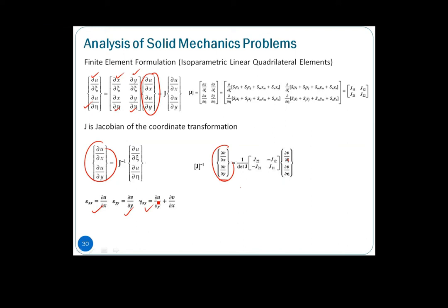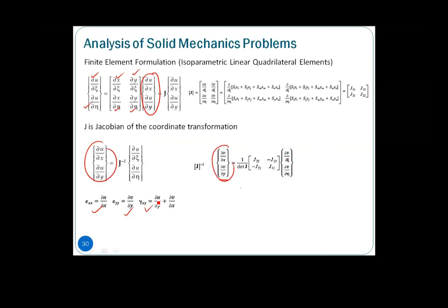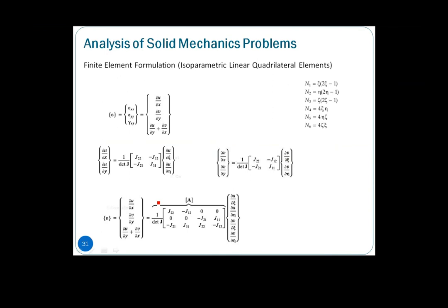Yeah, the whole procedure is still the same with isoparametrics. Just that previously we had 3 nodes, 6 nodes. Now under this linear quadrilateral element, we have 4 nodes. So here we rearrange them. Then we have this 3 times 4 matrix, right?